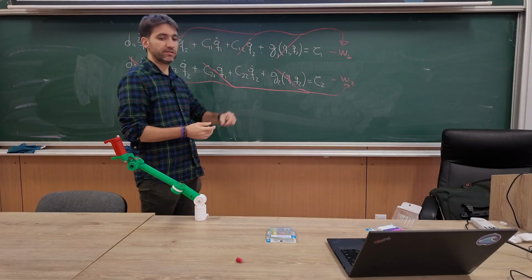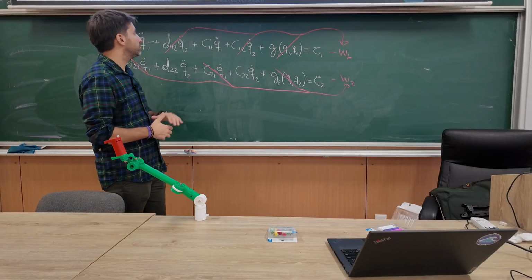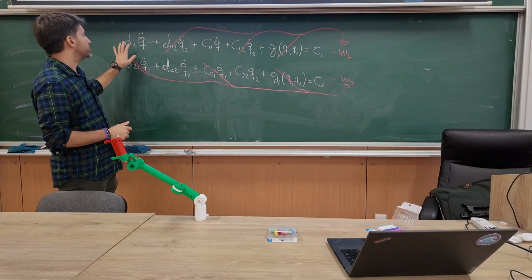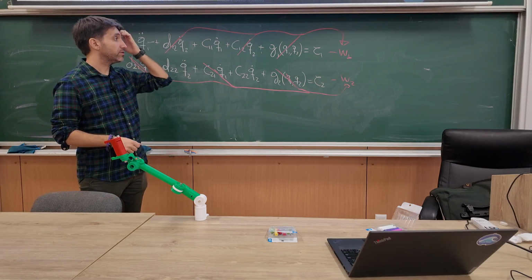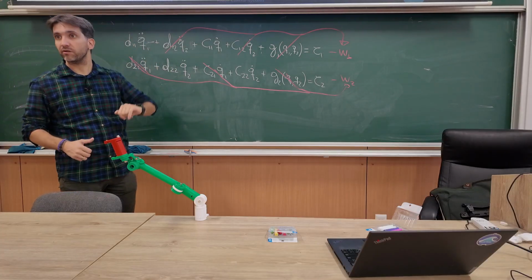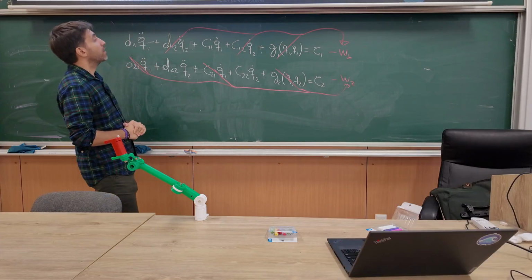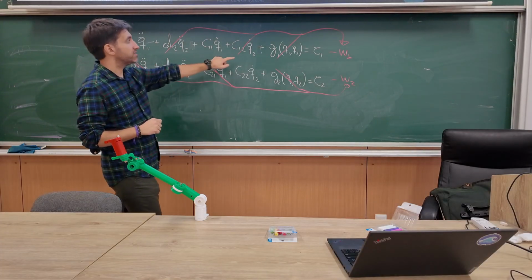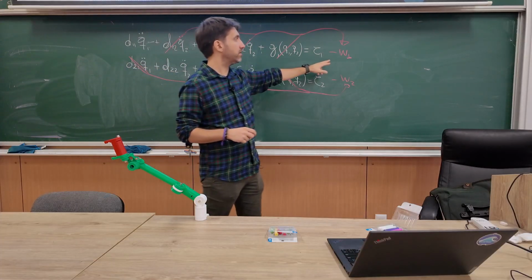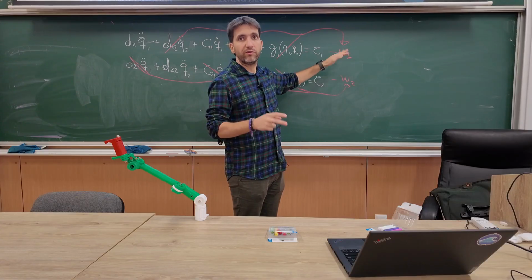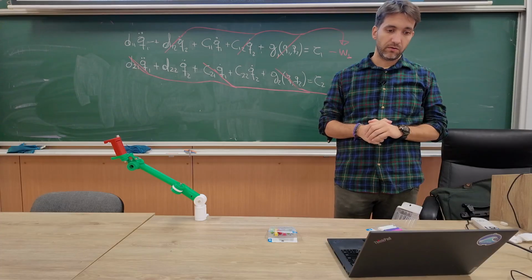That's the general form. So in the end, I have just the inertia part and the Coriolis part equal to the torque minus all these disturbances. As I said earlier, as long as these velocities and accelerations are small, I will end up having small disturbances. Good.